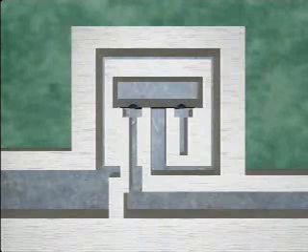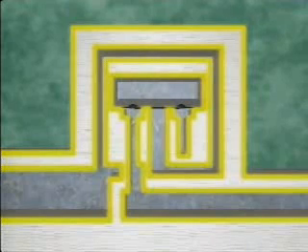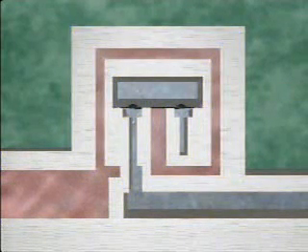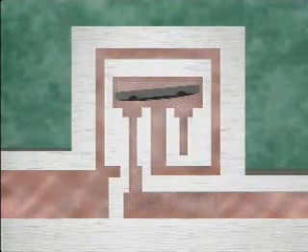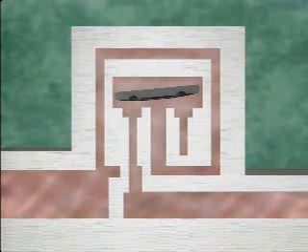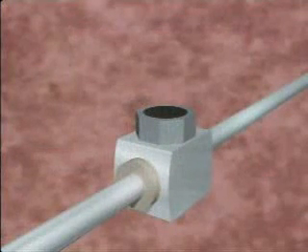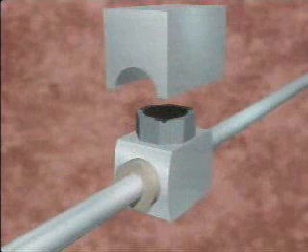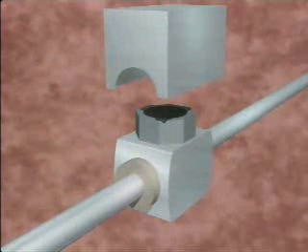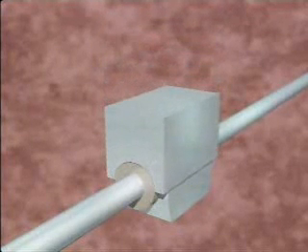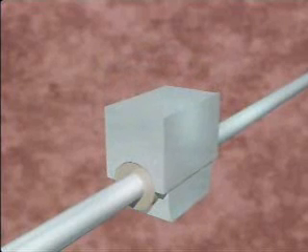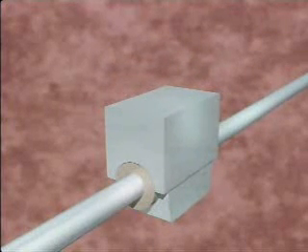Manufacturers provide various solutions to this problem. Some manufacturers make thermodynamic traps with double-walled bodies. Steam or condensate that enters a double-walled trap first flows around the outside of the internal parts and then into the trap. The warm condensate or steam keeps the internal parts at a relatively even temperature. Another way to protect a trap from adverse weather conditions is to use a bonnet cover. The bonnet is the top of the trap casing, and a bonnet cover is a metal cap that's placed over the top of the trap. The airspace between the cap and the trap body acts as an insulator and protects the trap from the weather.